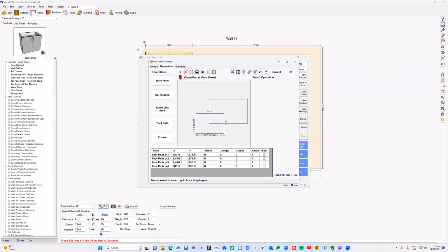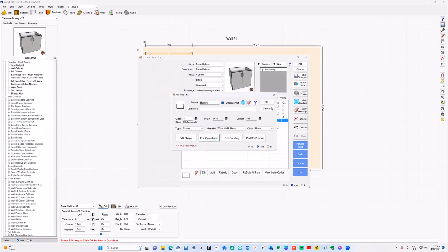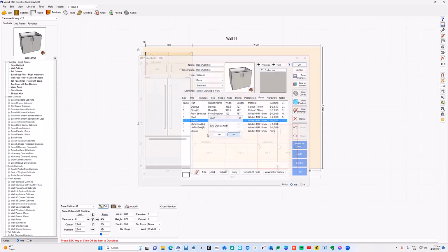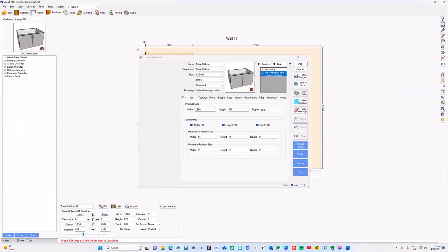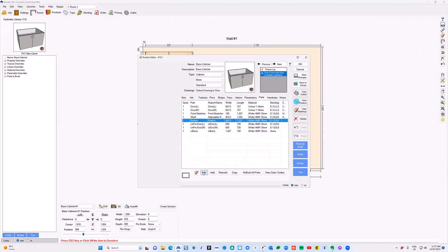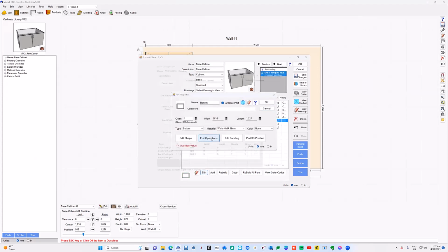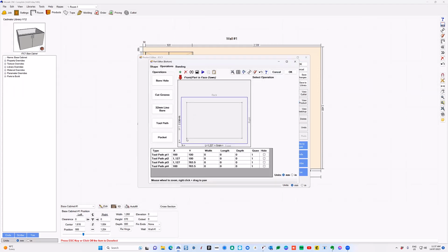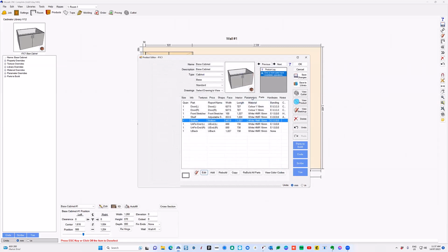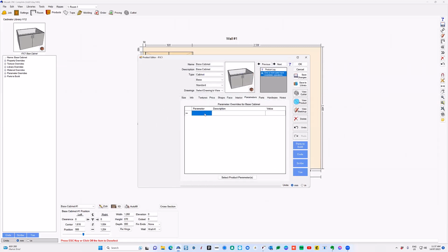So just to show you that difference, let's go cancel there and cancel again and cancel again. And I'm going to jump into this product, and rather than using my anchoring, if I'm planning on copying and pasting this and using it elsewhere, it is worth the time to go through and put your formulas on. And you don't just need to type in static values as well. It doesn't take long at all to do one extra step and go to a parameter control here and give yourself a size allowance.